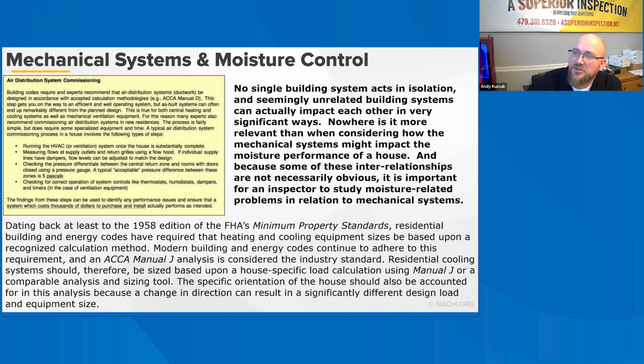Supplemental dehumidification, or enhanced moisture removal from HVAC equipment, is recommended in damp, humid regions as a means to control indoor moisture levels. In other areas with less prolonged periods of high humidity, these systems should still be considered based on their benefits, such as better control of indoor moisture, enhanced comfort, and integration with fresh air ventilation. For new basement foundations, supplemental dehumidification will also help remove moisture from the foundation as it dries, which can help prevent moisture problems in finished basements.